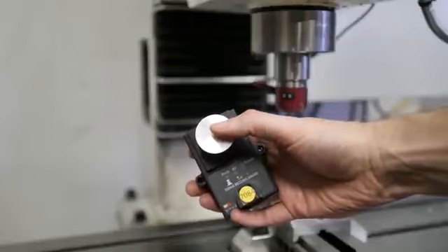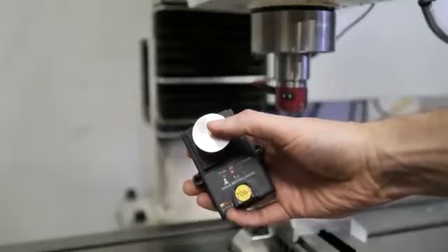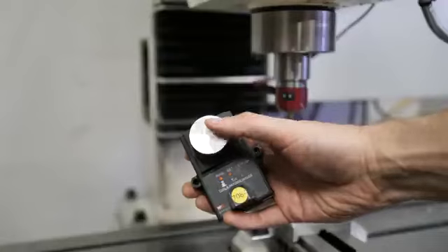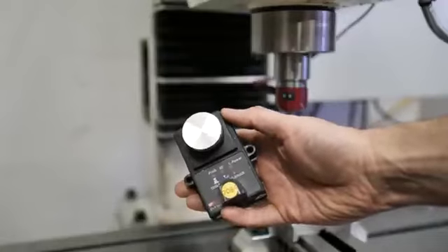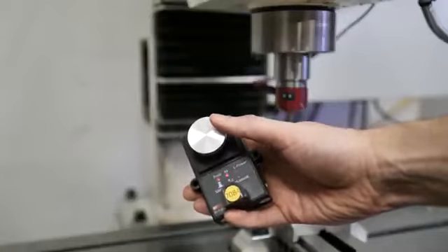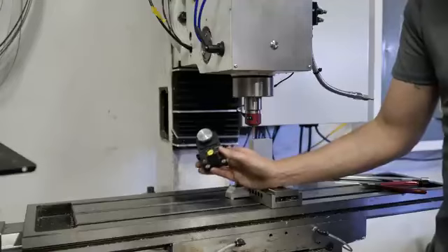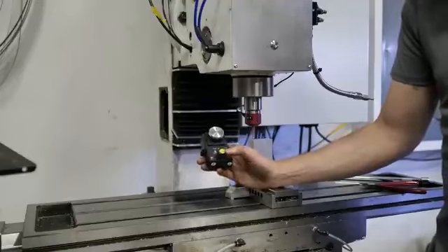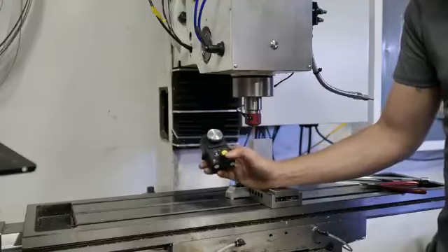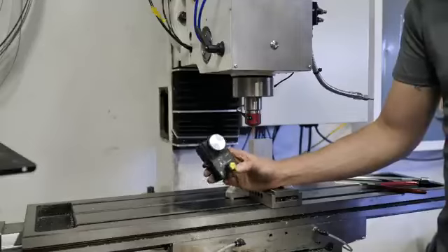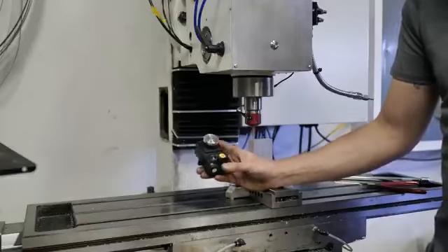When you click it the first time, it'll power up itself. It'll tell you that the probe is being clicked. The RF light here tells you it's communicating with the receiver. The low power light will come on if the battery is dying. It'll give you ample warning. When the battery finally does die, it is smart enough to recognize that it's not communicating with this anymore, and it'll activate your probe, so you're likely not going to crash into anything.